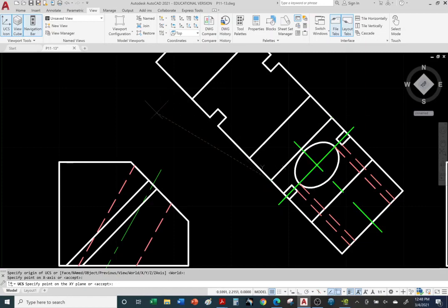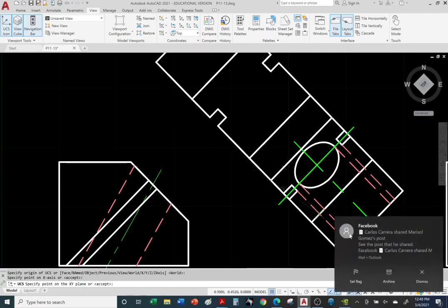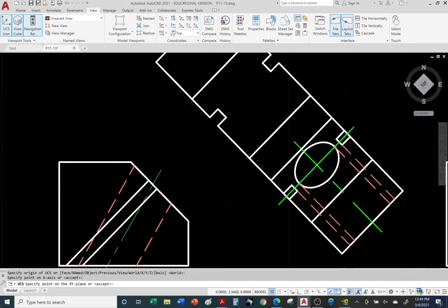Now I need to click one more time, and that's to define our x or our y. Do we want y to be positive in this direction or positive going downward? So we want our y to be positive in this direction. Notice if I hover over this bottom corner, the y flips downward. Now it's flipping upward, letting us know that this will be the positive direction.